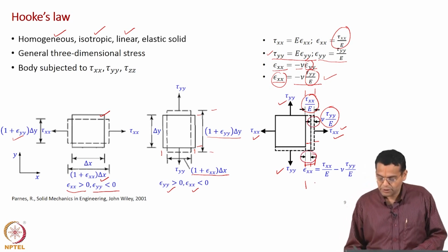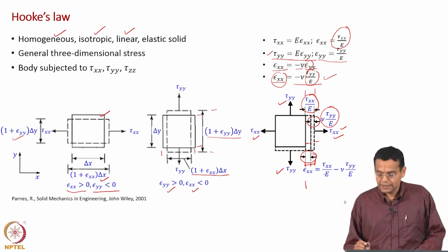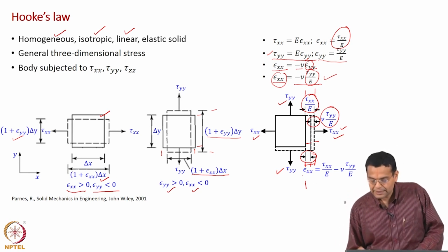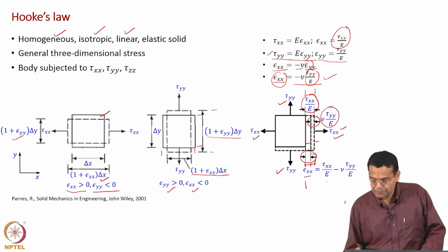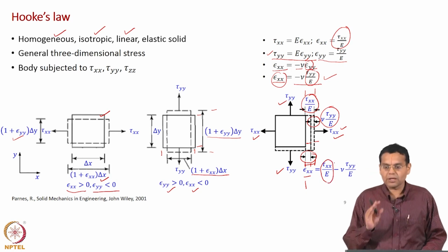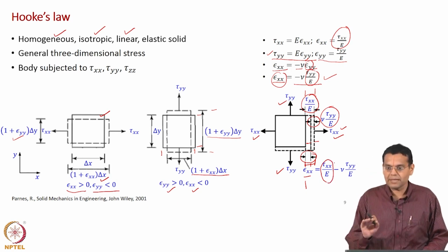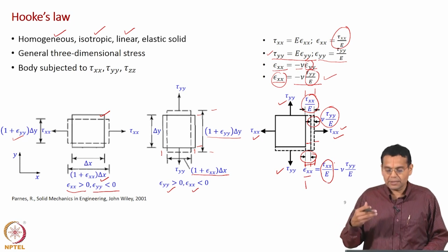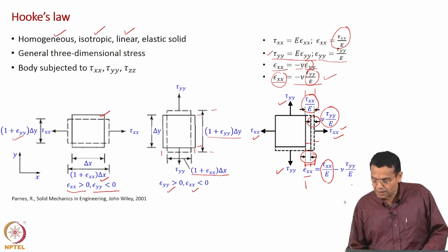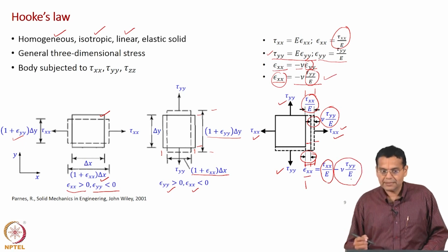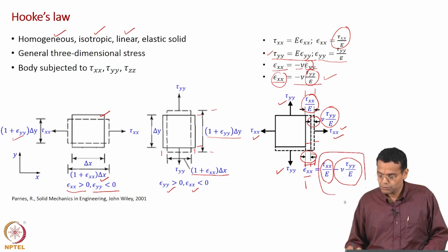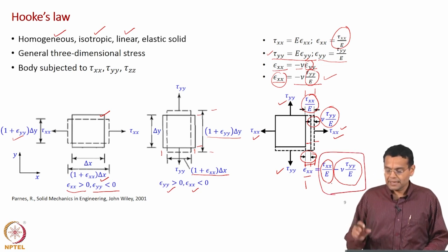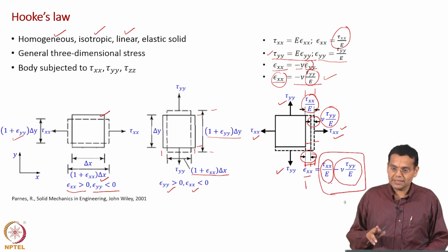Okay. So, in terms of equation that is shown geometrically, let us call the effective normal strain along x direction equal to tau xx by E. If there were no normal stress along y direction, only this would be the value, but because we had normal stress along y direction, it caused a contraction along the x direction which is minus nu tau yy by E, and so these two terms put together is the net normal strain along the x direction due to tau xx and tau yy.